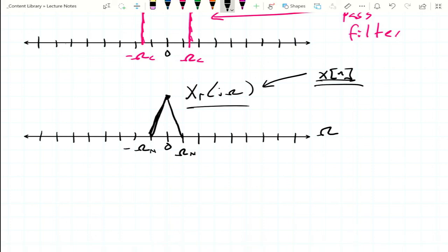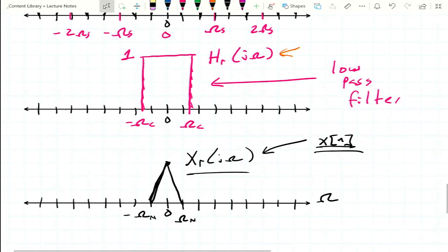Any questions about that? Wouldn't it be a bandpass filter? Because I thought low pass filters would only filter out like one side. Hey, that's a good question. So no, it is a low pass filter because it's centered around 0. Everything is symmetric around 0. So technically, this is higher frequency going out. Yeah, in practice, we kind of ignore the left-hand side here. And if you were to draw your vertical axis right there at 0, then you would see, well, we're just going out from 0 to omega c.